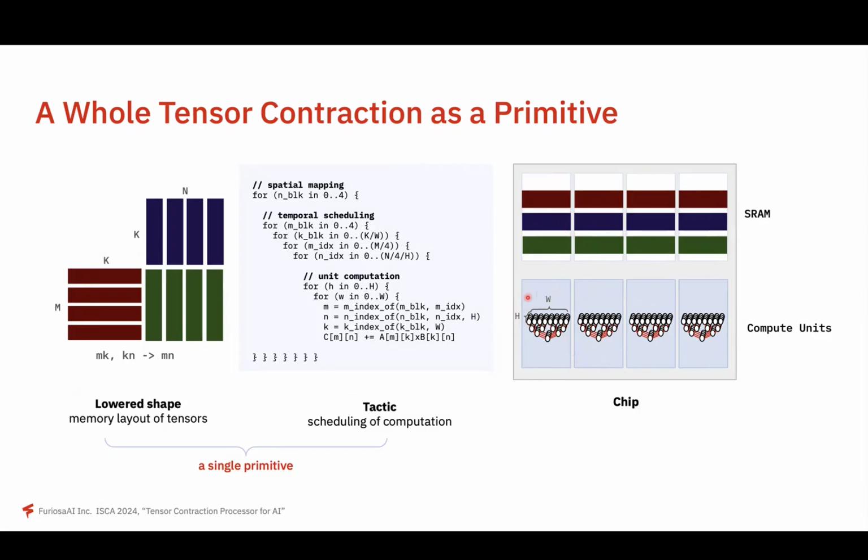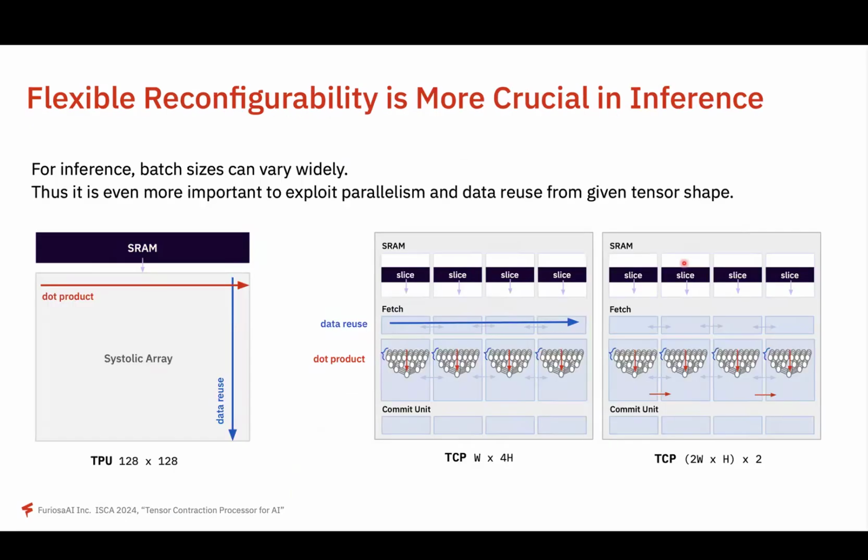In order to benefit from parallel computation, we need to partition the input and output matrices, and we need to store the partitioned data in a distributed way like this. But this is one of the possibilities. Depending on the matrix shape, sometimes we can use all the dot product engines to do a large dot product, or if the matrix size is small, we can run small dot products in parallel.